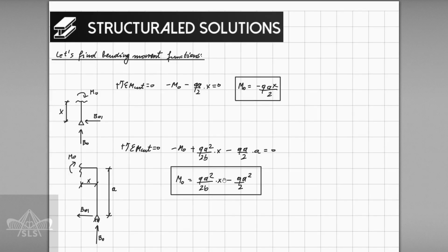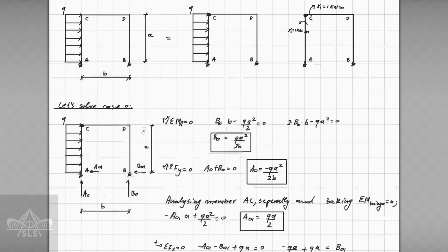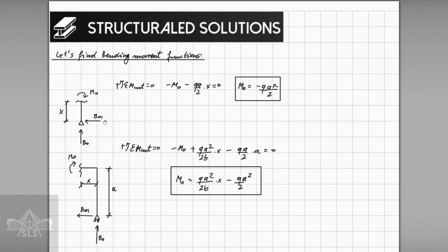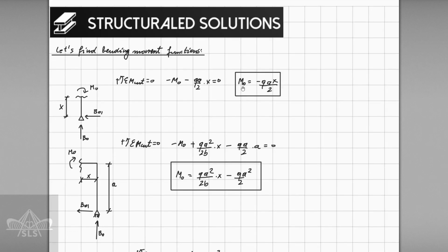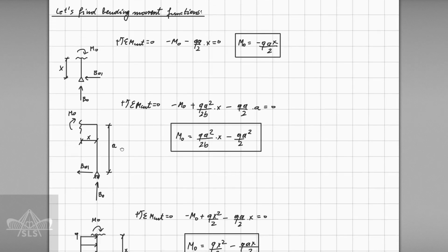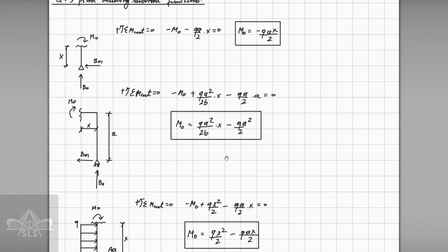In order for us to utilize the force method, the next step to be done is to determine the bending moment functions on the structure where we have discontinuities. And let's start by doing that. So I started from the right side, B we have here. I took this section cut from this side and I determined the bending moment function as shown here. Next, I decided to take the cut section from this part and define the bending moment function for these boundary conditions.